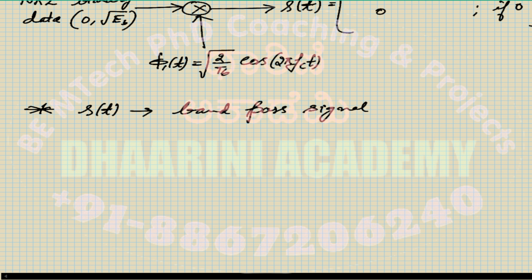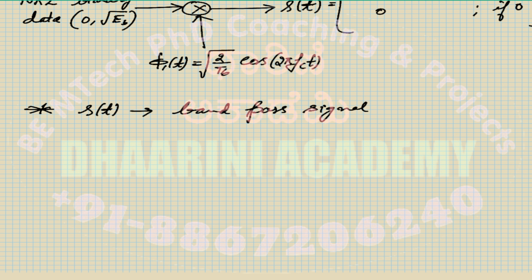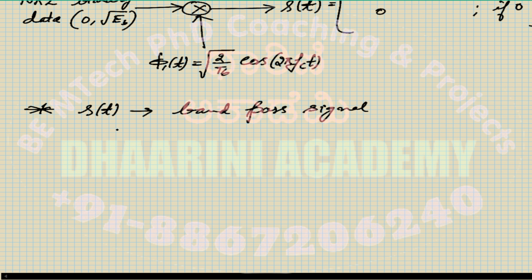And for any bandpass signal, we try to write its power spectral density in the following notation, right? So if s of t has a power spectral density SB of f, okay? So let's say s of t, I'll write an arrow mark to calculate the power spectral density. What do you mean by PSD? PSD gives you a plot. That plot gives you an idea that in s of t, on the frequency domain, at what frequency, how much power you are sending.